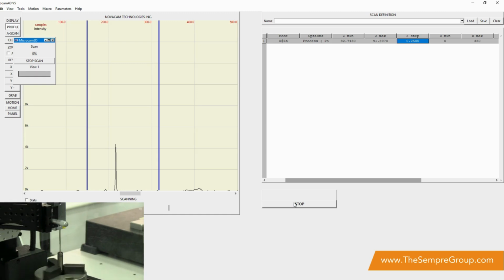So as you would have seen in the mode, there's lots of different types of scans that we can create. If we were using a roughness measurement, for example, we wouldn't use a spiral scan. We'd be looking to do a profile scan up the internal in the Z axis. Then we can iterate with our rotary stage, so we could take maybe 5 line profile scans on the internal of a component to depict the different roughnesses or look at length positions.